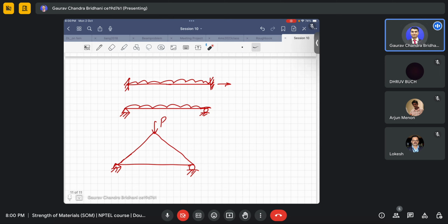So that means it is not coming as a fit. Usually, I am talking from a civil point of view, 5 centimeters is very small. You can't cut it with 5 centimeter precision at the site. You can do that precision using machines or good tools at the fabrication shed, but not at the site. It also costs and takes time, so there is a loss. So what the site engineer will do is say, okay, put it there.